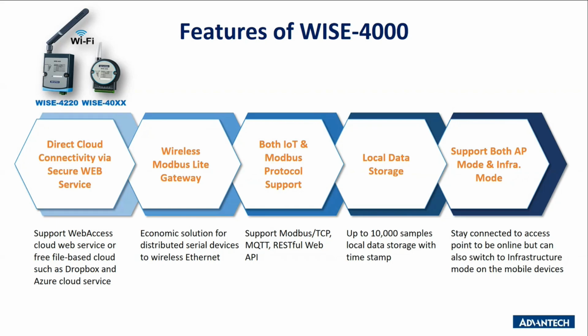Besides, you can also use this WISE 4000 as a Modbus RTU master because it has RS485 on board, and you can convert the data to Modbus RTU after you have collected the Modbus data from your slave device. There's also local data storage in the WISE 4000 series.